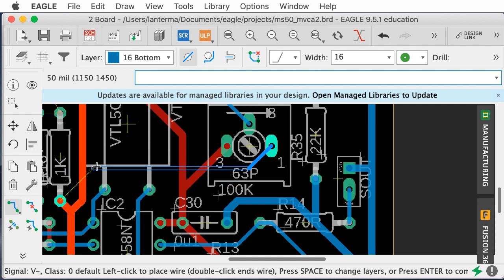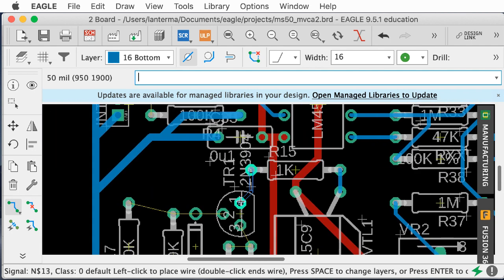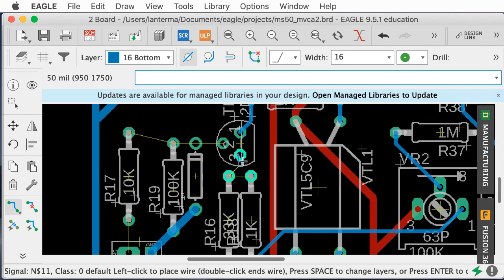Okay, now we're sort of in the tricky zones. I'm crossing over the chips, so I want to be very careful about not crossing with the same color. These guys hook together. This guy hooks to this transistor. Transistors tend to be kind of weird, so I like to route these coming out of the transistor. You know, anything where the pinout doesn't line up on the grid nicely.